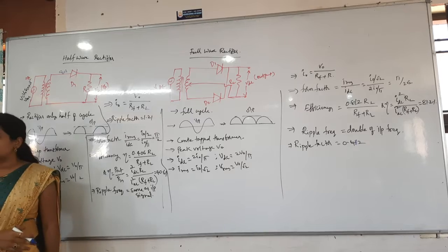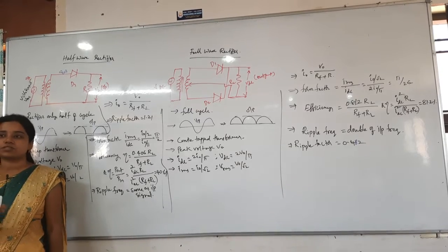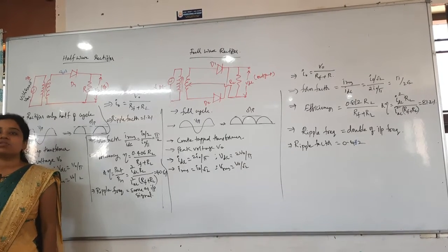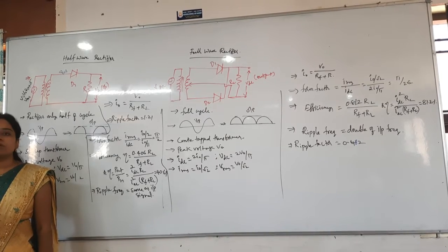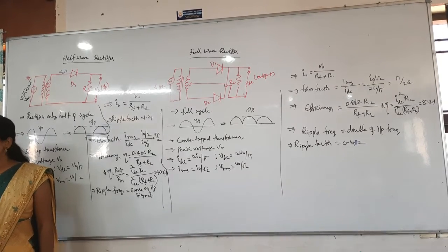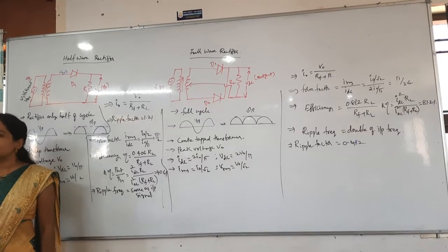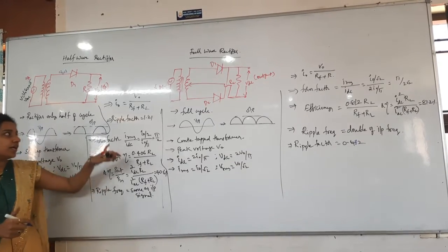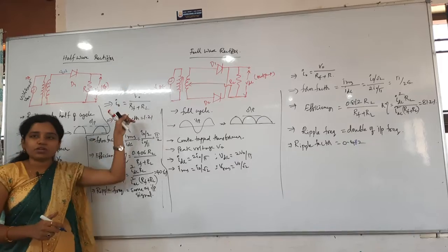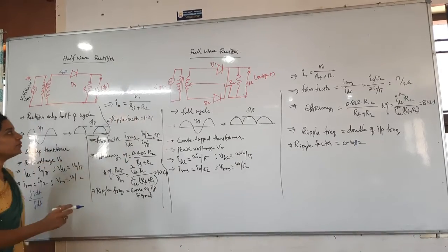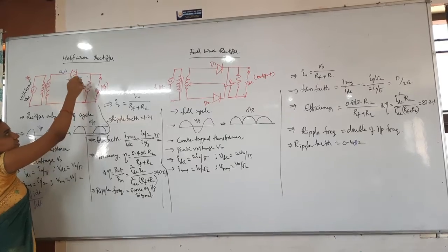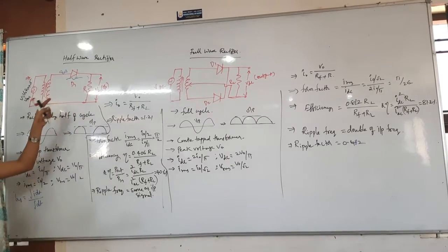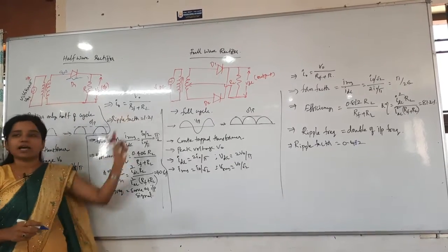Whenever they ask about the resistance, the diode will also have resistance. To decrease that resistance, which process do we do? Doping. By doping we improve the charge carriers, so the resistance decreases. So here the current is the voltage by resistance. The voltage is V naught and the resistance is in series combination of this and this, so I have taken RF plus RL.